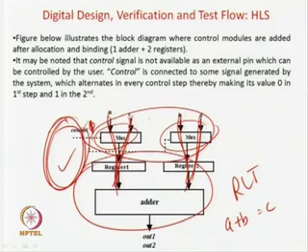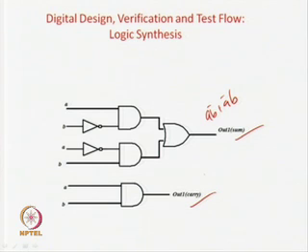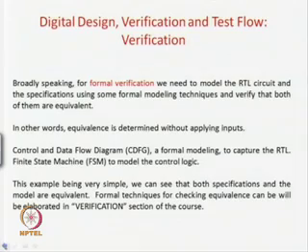Now, you have to verify whether it is really doable by this circuit, because this circuit we have got after logic synthesis. So, the same adder at the block level, where we say A plus B or C plus D, is now converted into something like this. So, you have to formally say that both of them are equivalent. For that we have to do something called formal verification. In case of the adder it was only 2 bits, so you could try 0 0, 0 1, 1 0 and 1 1, but if it is a 1000 input case, then you are in a big problem. So, in this case you have to do that formally. We will be learning that in our formal verification module. What we will do is model the circuit in some formal models, and then try to verify mathematically whether everything is proper or not.